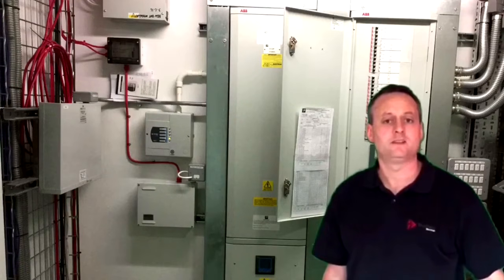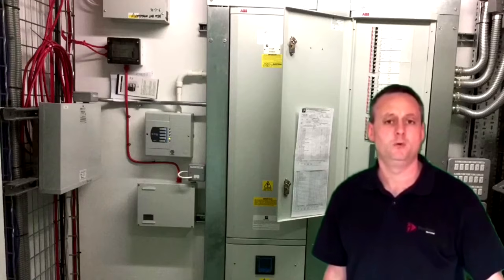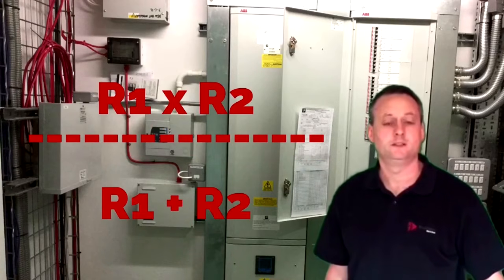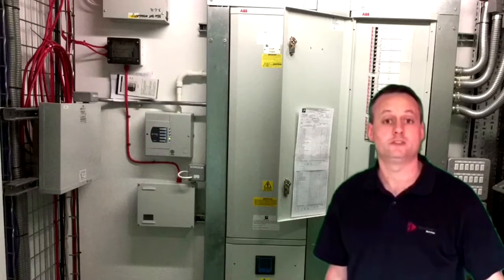Another formula that makes the total resistance of 2 resistors connected in parallel more simple is the one where it's product over sum. In other words, we take the 2 resistor values and multiply them together, and we put it over the 2 resistors added together, and therefore work the calculation out for the total resistance in that circuit.